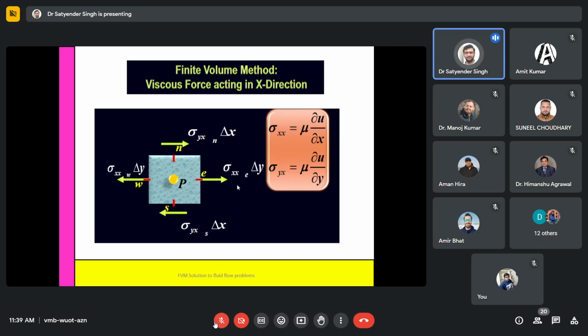The reason is that near the wall viscous forces and shear dominate, and there is no slip, which we consider mathematically. From zero, velocity starts increasing and attains a maximum at the center, and the same is replicated at the top wall. So a parabola is generally formed for the velocity profile in fully developed flow.